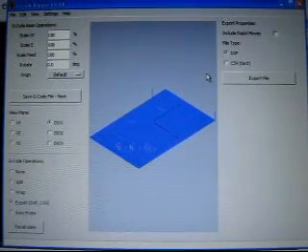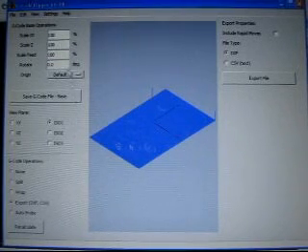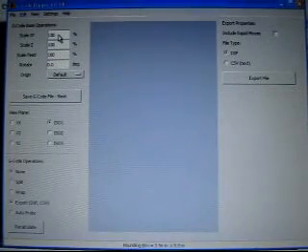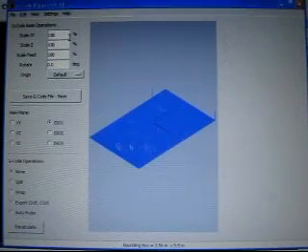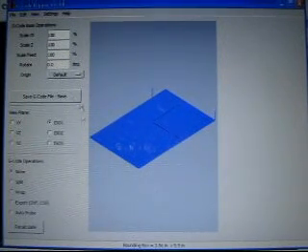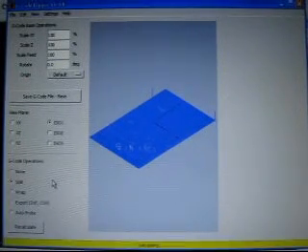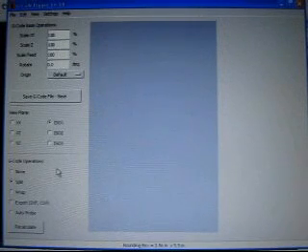Alright, there's a lot of things you could do with this program. You can simply alter your scale for your G-code. Scale in the XY, scale in the Z. You could scale your feed. You could rotate it, stuff like that, and then repost the code. You can split it.